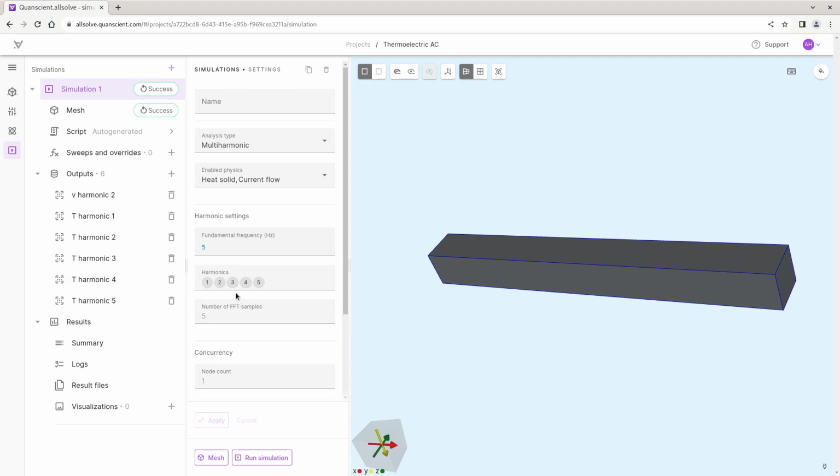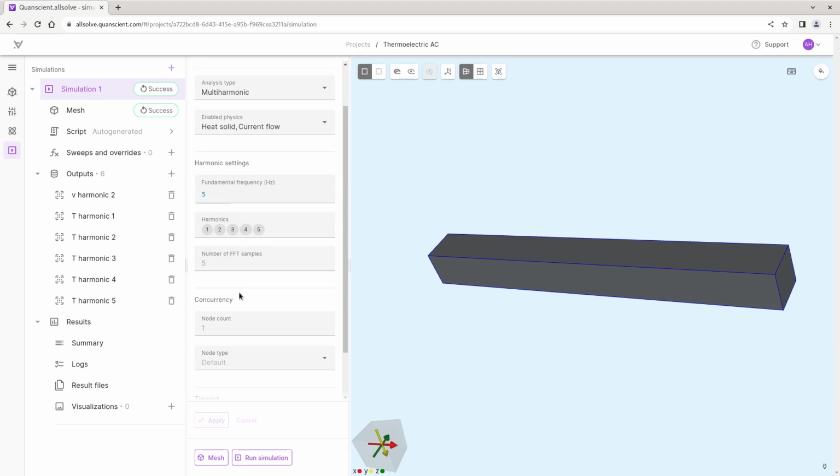But you will get a crystal clear frequency response of your solution. You will not have to do transient analysis, so this will make things easier to set up, and you will very likely get the solution faster than with a transient analysis, especially for situations like vibration with low losses, where reaching the steady state takes forever in the transient analysis.